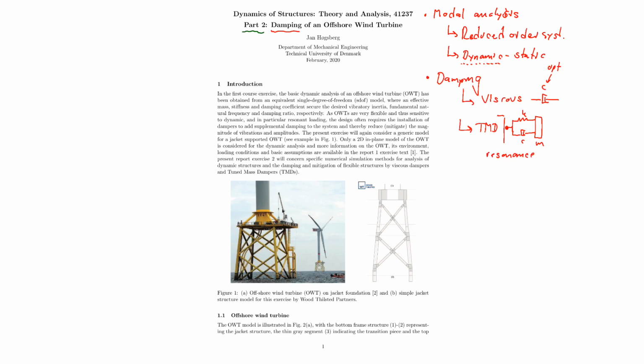We have an interplay between K and M, and that gives us a natural frequency, basically as K divided by M. So this additional damper natural frequency then maximizes the energy dissipation in the dashpot here, and thereby a TMD is often more efficient than a viscous damper. But it all depends on the loading and the vibration modes and where you can apply the damper.